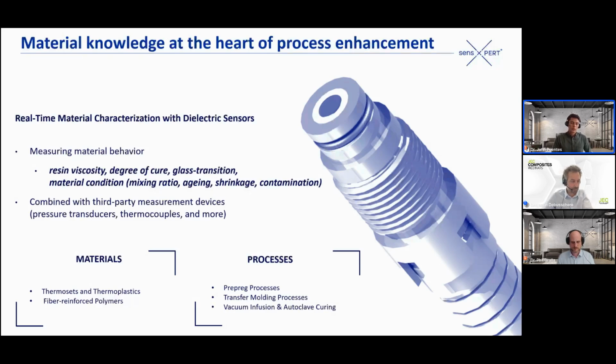and the post-curing in autoclave. Depending on the case study that you have for the different problem, we can target this solution to perhaps degree of cure. If you're interested in the mechanical part, the glass transition temperature. And there are some additional things that one can do with the electrics, such as measuring mixing ratios, problems within the system, aging through the history of transportation of the material, and so on.